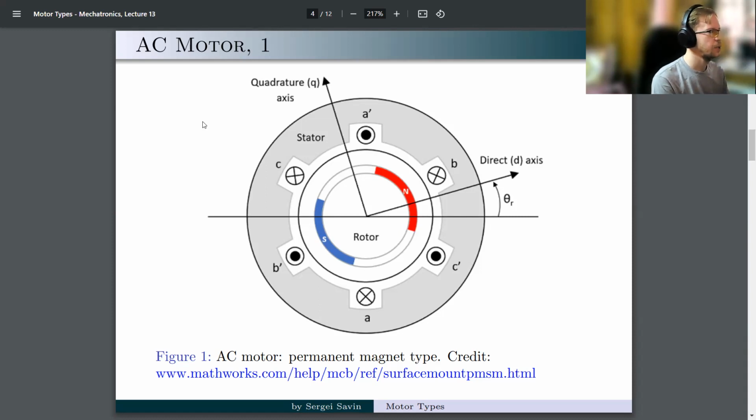The brushes act like a switchboard, automated based on the orientation of the shaft. Different parts of the circuit are connected, and the direction of the current changes. This is how you achieve continuous rotation. In the simplest example of a DC motor, the polarity in the same coil would be changed, and we would achieve motion. Actual DC motors are a little more complicated than that, but the idea is still that you use brushes to automatically recommutate.